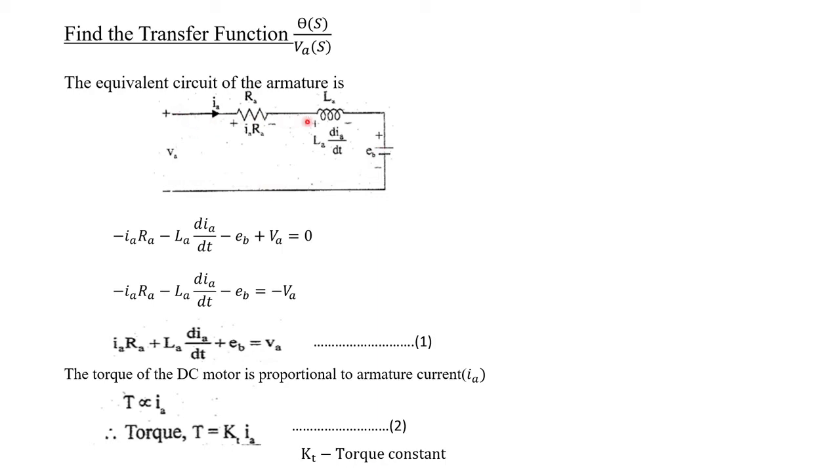So now after going through these paths, again we are ending here. Okay, so we are coming from here to here, it is minus to plus, so this will be plus, that is considered as voltage rise. The voltage value is VA, okay, that is equal to 0. So in this way we can apply KVL in this closed path.